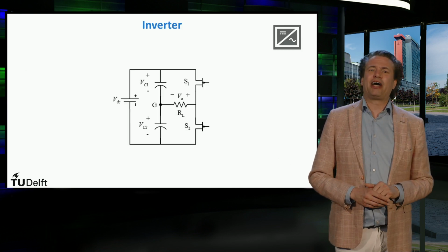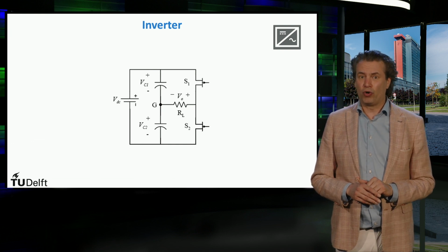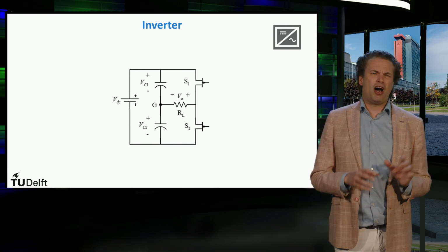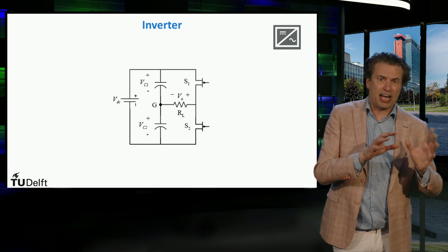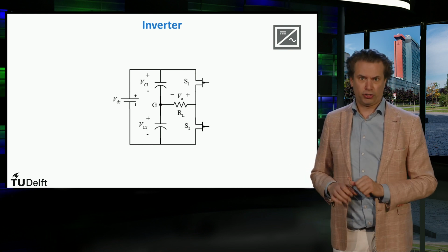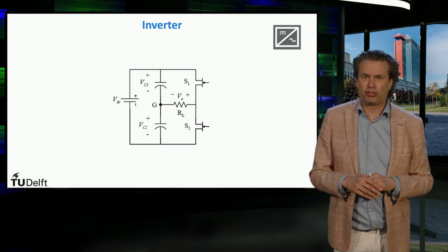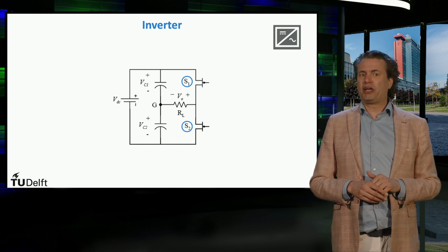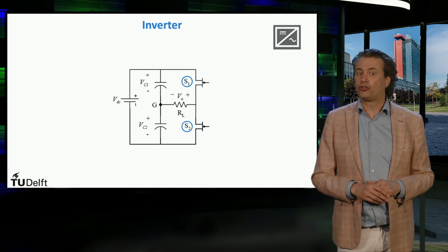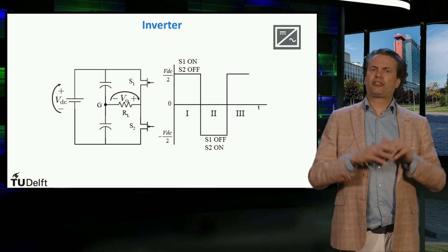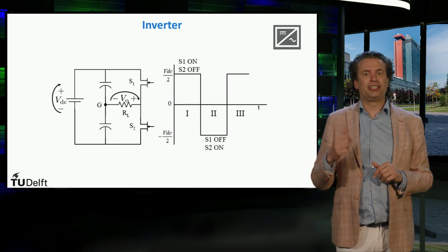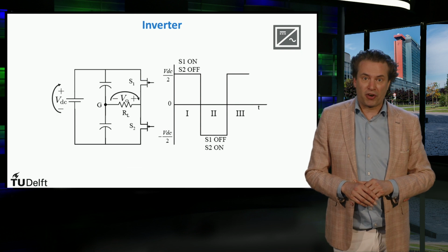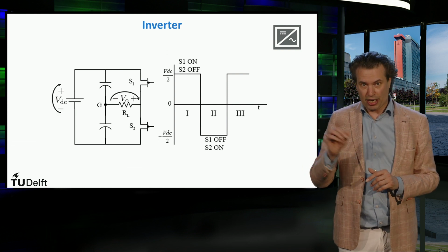We will start this lecture by understanding the principles of how an inverter works for the conversion from direct to alternating current. Power converters can contain uncontrollable semiconductor devices like the diode or controllable semiconductor devices like transistors and MOSFETs, which can be used as switches. Let's assume that switch S1 and switch S2 in the figure are controllable switches. Let's consider that the circuit shown has a constant DC voltage at the input. The figure on the right is the output voltage under the operation condition I will discuss now.